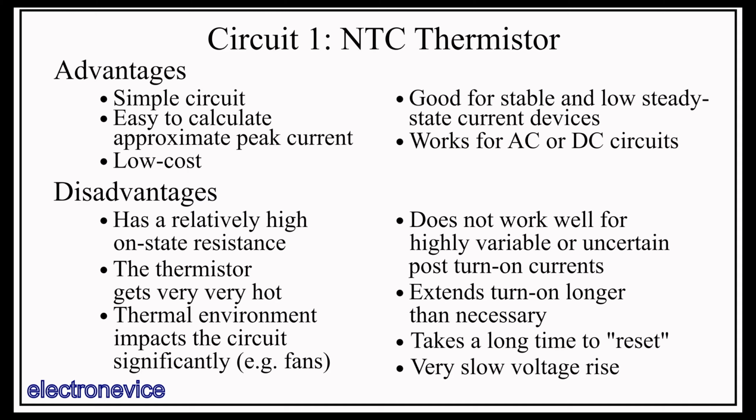The problem is, this tends to happen on the 100 millisecond scale or less, so under these conditions, your subsequent circuits might false start 10 times or more before finally stabilizing. This is generally not a good way to do a clean startup, and so you may need to add components to coordinate power up, thereby defeating the whole purpose of having the low-cost NTC to start with. This slow voltage rise, of course, may not matter at all for many projects, in which case it's merely something to keep in mind while designing.